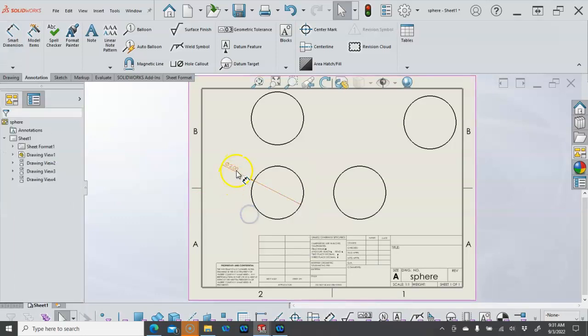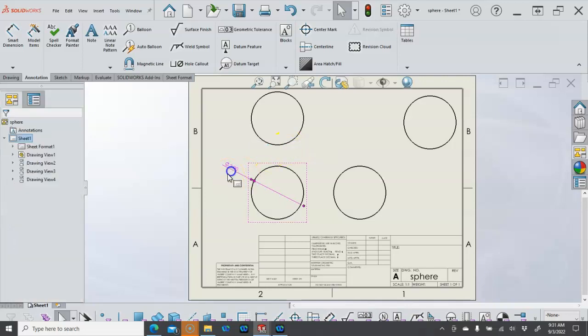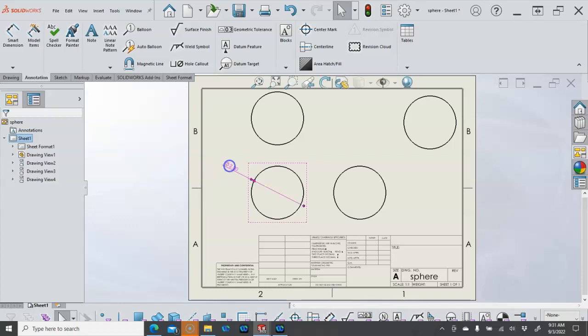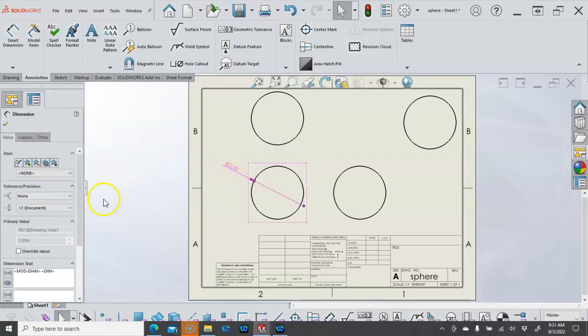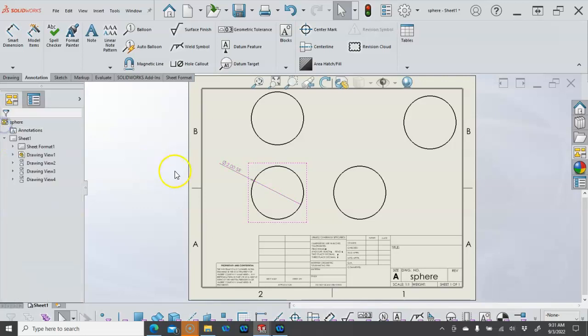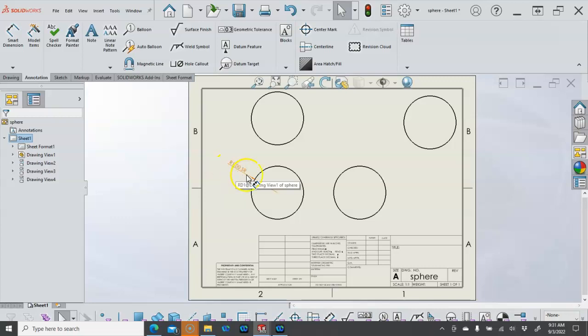Right click, go into select, and then, oh, I don't remember that one, but display as radius, display as diameter, so that's handy. But if we go SR, spherical radius, then let's go ahead and switch that over to, makes a little more sense, radius 1 inch SR.